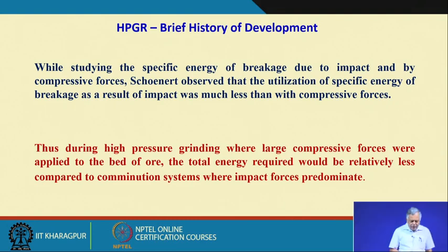So, during high pressure grinding, where large compressive forces are applied to the bed of ore, because you are squeezing it, the total energy required would be relatively less compared to comminution systems where impact forces predominate.